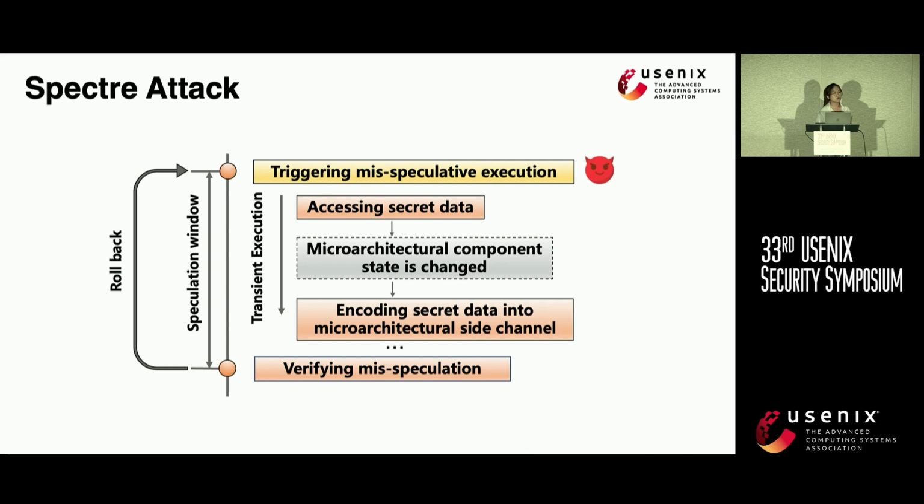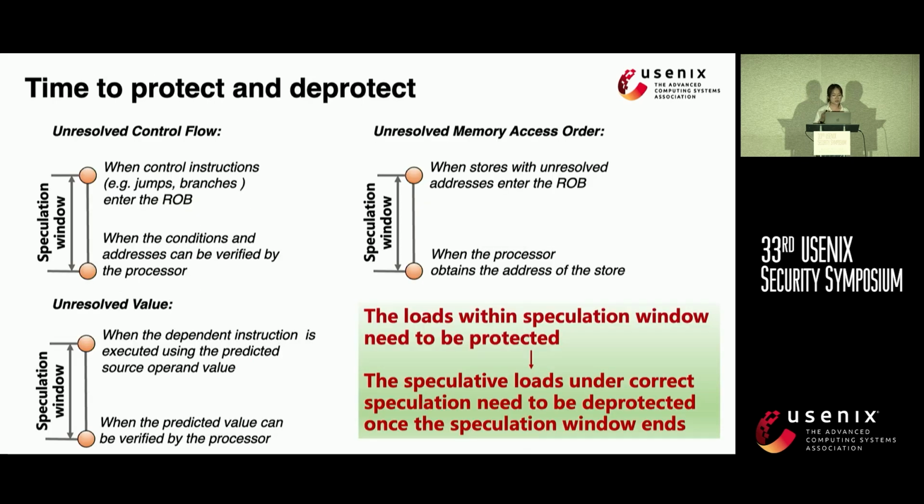It's important for reducing performance overhead to lift the protection timely, since most speculation is correct under normal programs. Therefore, the loads within the speculation window need to be protected, and the speculative loads under correct speculation need to be deprotected once the speculation window ends.